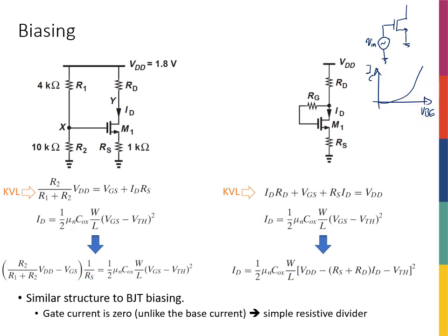So we have a very similar situation with MOSFETs. If I want this thing to work as an amplifier, I need to make sure that the transistor is on and it is in saturation, right? So if this is VGS of the MOSFET, and this is the ID, the drain current, I know that I don't have an exponential relationship, I have a quadratic relationship, but still the same story. I care about the slope of this curve, as we defined the GM last time. If I want a good and decent amount of GM, I have to be somewhere around here, right?